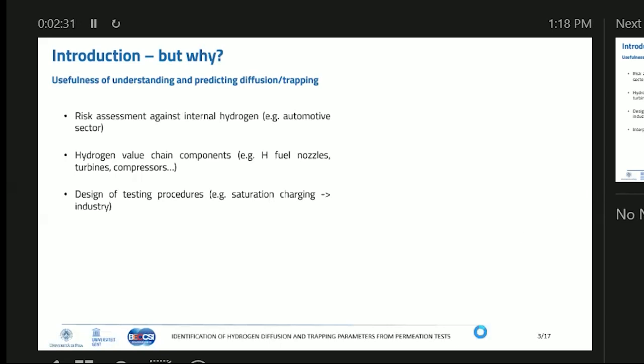But another reason could be, for example, to interpret mechanical testing results. I distinctly remember one paper, which I can't find anymore, where they compared experimental hydrogen depth inside of an in situ charged specimen and predicted hydrogen penetration depth. From the difference between these two, they made some conclusions. They observed one by watching the fractography. This is a way in which information on diffusion helps us interpret mechanical testing. But also, what we are trying to do in a different context is mapping, for example, by simulation inside of our ex situ test specimens. So there are many reasons why someone may be interested in this.